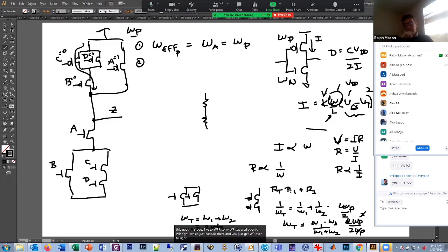If you take two resistors in parallel, and this is R and this is R, the total resistance is half, it's just R over 2. And if I take 3, it's R over 3 and so on. So when they're the same size and parallel, it's easy to calculate. That's why I'm assuming these W's are the same, just to make the calculation easier.